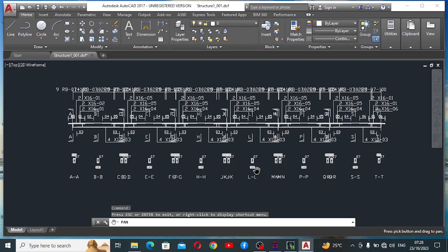4y12. So you can equally reduce this y16. Maybe I'm now going for y20. If you go for y20, the number of bars here will be reduced. So that is the essence of design. And when you're using this, it makes it easier.